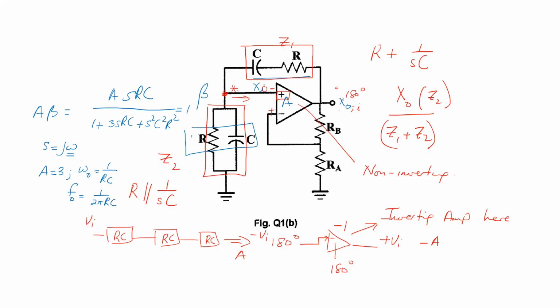So the thing about this particular type of oscillator, and this is something that you're going to see in all the other networks as well too, these things have to match. So this capacitor and this capacitor have to be equal. This resistor and this resistor have to be equal or as close as possible. And we spoke about that too when we were talking about using real components. If you're buying components off the shelf, resistors typically have a 5% tolerance, right? Capacitors have 5 to 10.